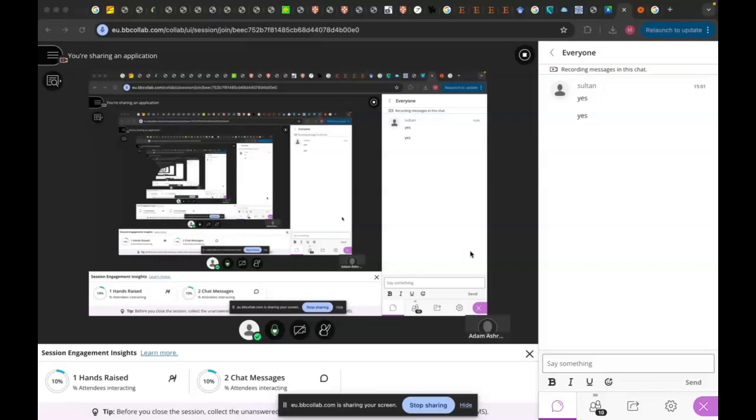Is there an issue? Do you have the student license? Yeah, this is crashing. Maybe your laptop is the university laptop? The student license doesn't let you use more than 4 cores. If you use more than 4 cores, the application won't start. The student license is also limited in the number of mesh elements. So you should follow the guidelines they mentioned. Fewer mesh elements, 3,000 elements. In terms of number of cores, make it 2 or 4 maximum.